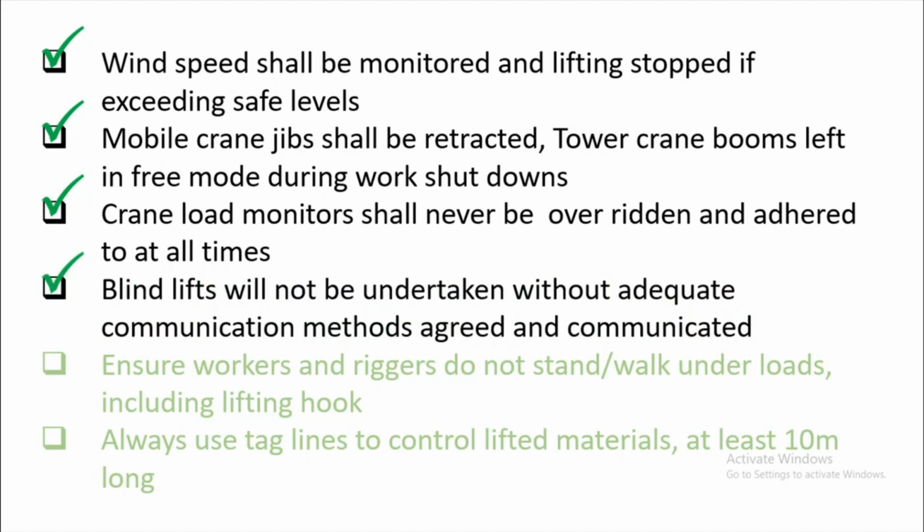Blind lifts will not be undertaken without adequate communication methods agreed and communicated. So this is very important. Where the operator cannot see the load at all times, make sure that there is adequate communication between the operators and the riggers when they are doing the lifting operations, and make sure all of this is communicated, including the affected work area, to avoid any incident.